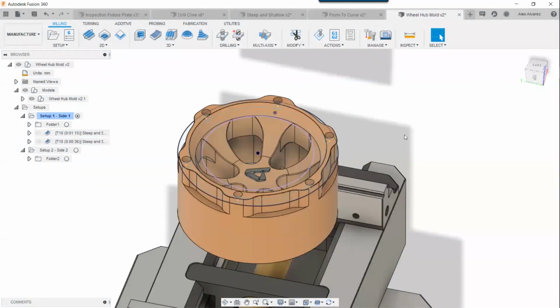If you're familiar with different CAM software, they'll refer to this as a barrel strategy. Essentially, if you have a 4th axis indexing machine with rotary capabilities, you can lock one of the axes, and it's going to rotate the model around, in this case, the x-axis, and create toolpaths on that specific model.